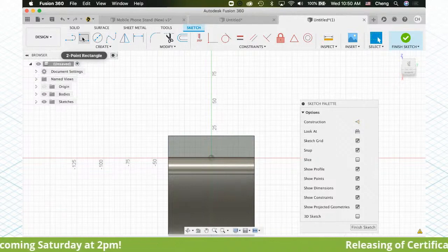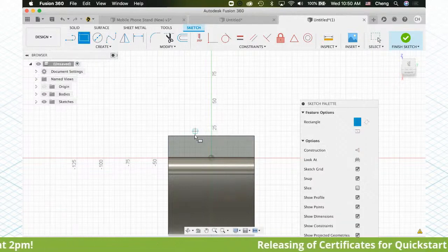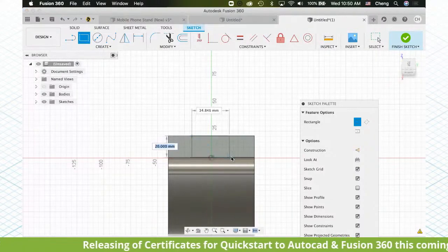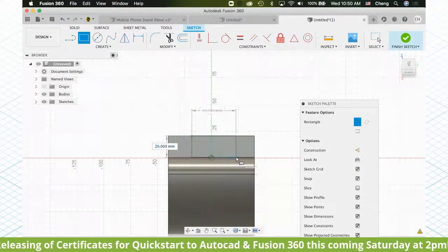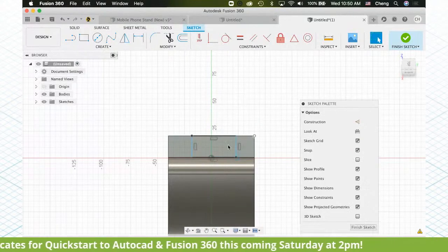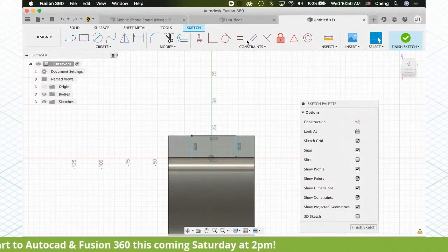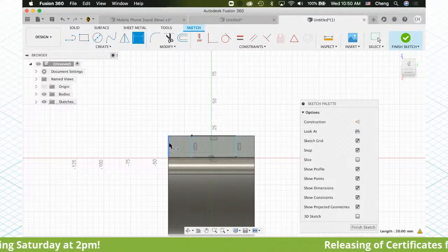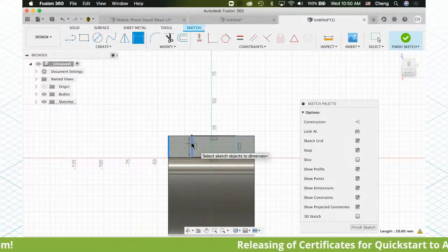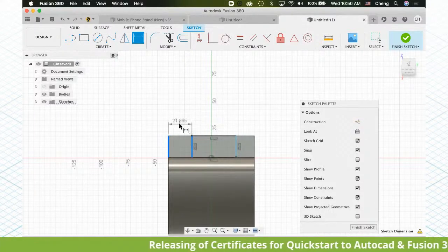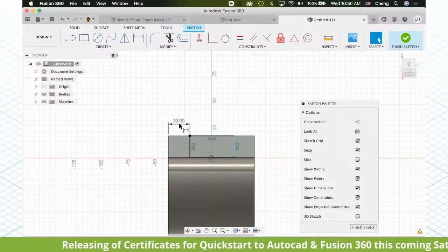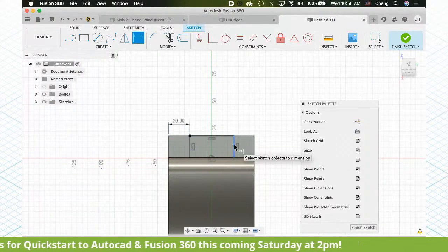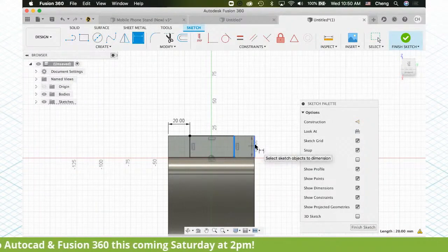So I'm going to draw a rectangular shape, from the center to the second point over here. I will have two indications appear. Then I put in a dimension. I want to put in dimensions on the left-hand side, between the geometry and the inside geometry. This is to be 20. One more time, dimensions, the inside geometry to the outside geometry